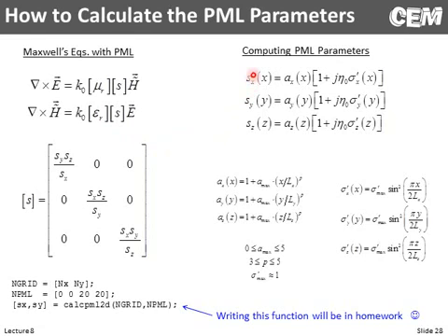Okay, so our PML terms have potentially some amplitude, some maximum value, if you will. We're just going to make the real part 1, and here we have the imaginary part. And we put it in this form. This is very similar to how loss is incorporated, or the conductivity is incorporated into a complex dielectric constant. We're borrowing from that. So this amplitude is really grading the severity of the PML, if you will. So it's going to start off as 1, and it's going to get larger from there, according to this ratio.